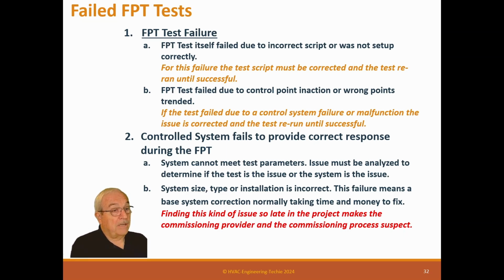The problem is that unit took 3 months to fix because they had to re-engineer it. They had to order a new unit and rip that out. I supervised changing the controls to an analog output. We made sure it wasn't a step sequence, since the humidifier, being 10 times smaller, didn't have to be. So what happened here is it delayed the opening of the project.